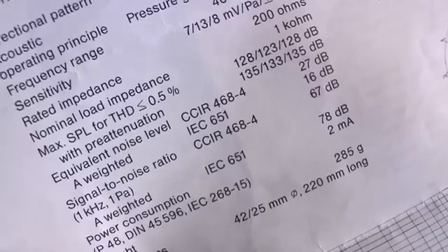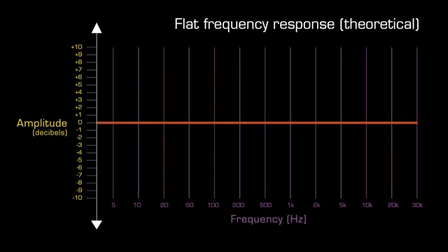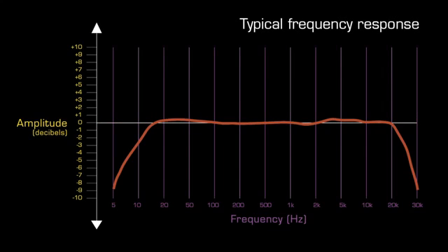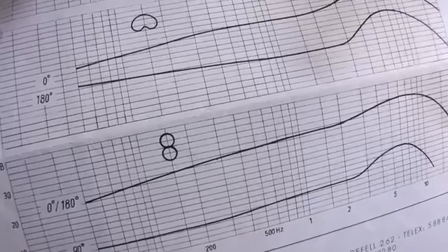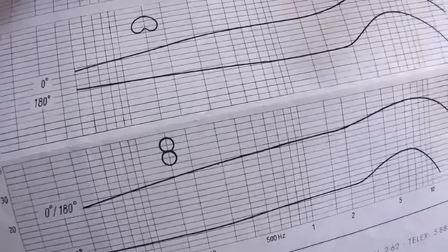The primary things to look out for are frequency response. Unless we have a specific need, we will want this to be as wide and flat as possible. This means at least 20 Hz to 20 kHz with no significant changes at any frequency. We may not always want a flat response and prefer a response that boosts some frequencies, perhaps in order to add clarity or definition, but either way we can check the frequency graph if one is available.